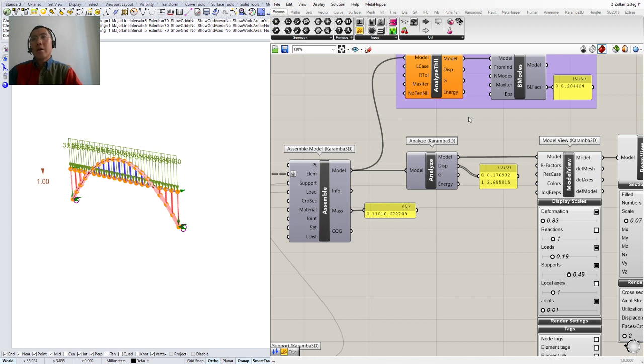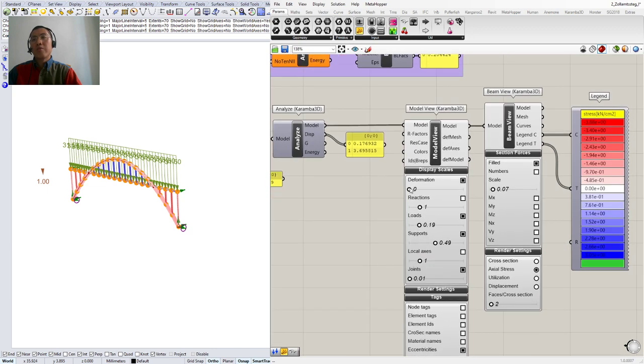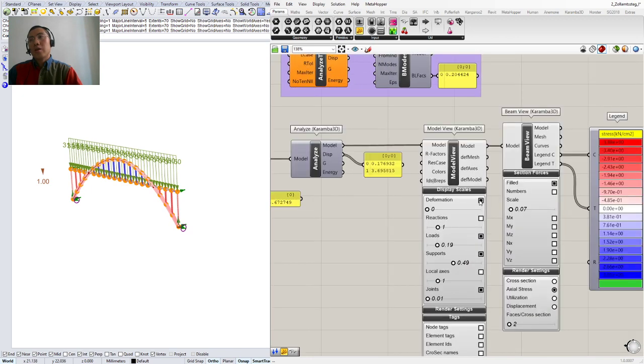So, as you all remember, last week Clemens showed you how we made this one-dimensional bridge, this arch bridge. What I want to explain, because some people were asking, is why in the model view we have set deformation to 0. Basically, what we are doing is taking the moment curves to generate the geometry of our arch. We can either leave the deformation turned on or off, it would have no difference, but if we were to activate the deformation,